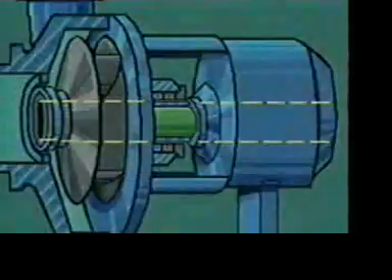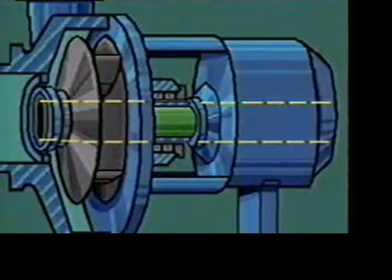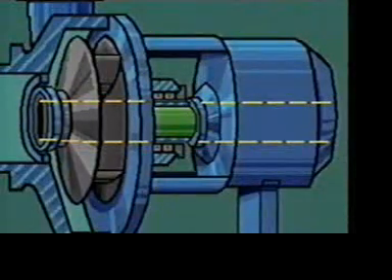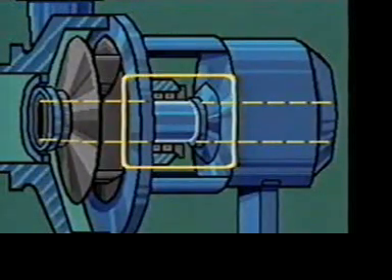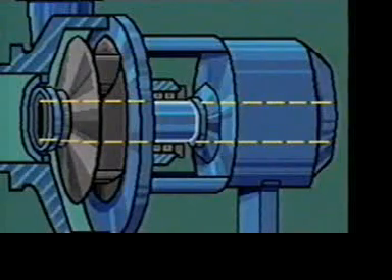The internal parts of a centrifugal pump are mounted on the pump shaft. It's a single piece of metal that's been machined to fit the pump perfectly. The shaft is usually made of stainless steel or some other corrosion-resistant material. And for a very practical reason, replacing broken or worn-out shafts is expensive. Some pumps have a shaft sleeve, or metal cylinder that fits over the shaft and protects it from damage. It's easier and cheaper to replace this sleeve than the shaft itself.